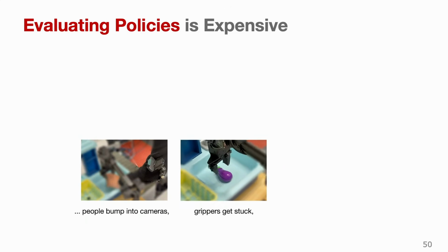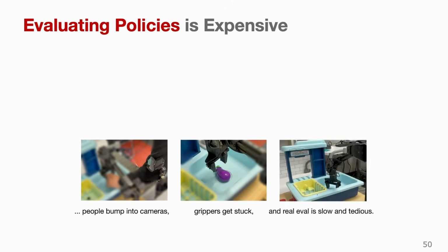For example, if you have a third-person camera mounted near your robot, and you collect some data and train your policy on it, and then someone bumps into the camera, and now your camera is in a different pose or position. Maybe you didn't calibrate, so it will be out of distribution and it doesn't work anymore. Maybe you have to collect new data, fine-tune, I don't know.